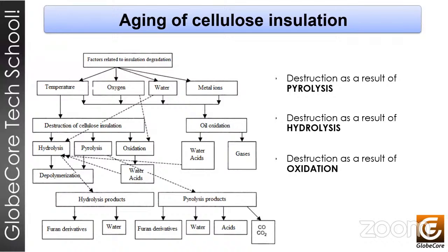The main indicators of accelerated aging of insulation are increased temperature, increased humidity of the winding insulation, oxygen, and oil aging products. A significant indicator of the oil oxidation, even with a low oxygen content, is an increase in the content of metals, specifically copper, in the oil.